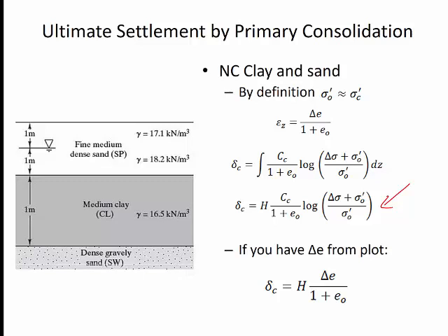The reason I know that is because this coefficient here is the compression index, meaning that the stress state the soil is in right now is the same as the maximum past stress it has ever felt. As you add more stress to the soil, it will follow the virgin curve line.